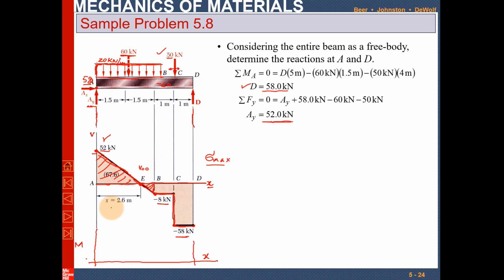The third method is that you find the bending moment equation, and then from the bending moment equation you put the value of x and plot, but it will consume too much time. So better is to use a short method.